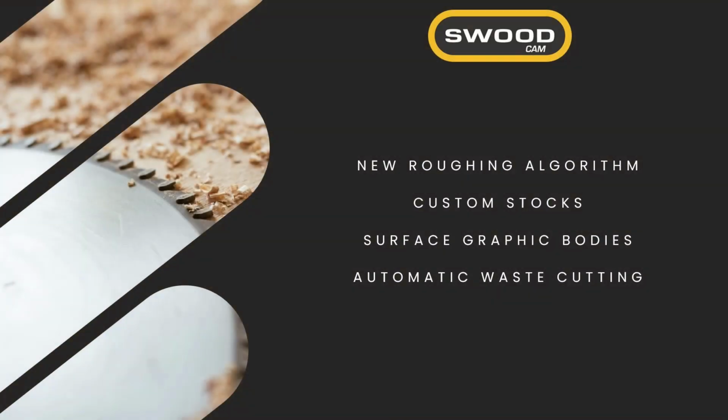Moving on to SWOOD CAM, we will focus on two main areas: the introduction of new 5-axis features and off-cut machinings. Regarding 5-axis machinings, we have developed a new algorithm for 3D roughing, which includes the ability to define custom stock for 3D rough milling, as well as the option to surface graphic bodies. Lastly, we have introduced machinings that automatically cut the waste into small pieces.